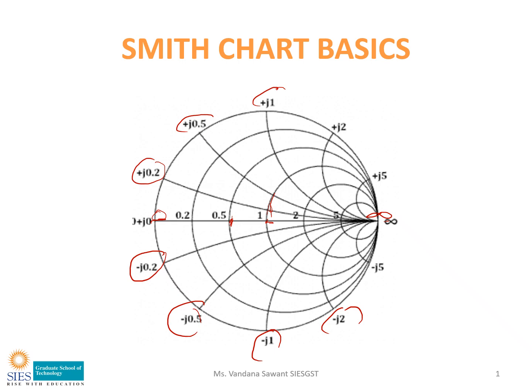When we want to plot any point on the Smith chart, we have to plot with respect to the r and jX values. For example, if you want to plot the impedance Z equal to 1 plus j1, this 1 indicates r, and this j1 indicates the jX value.